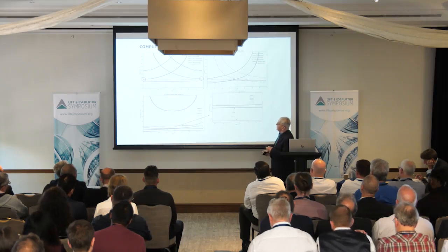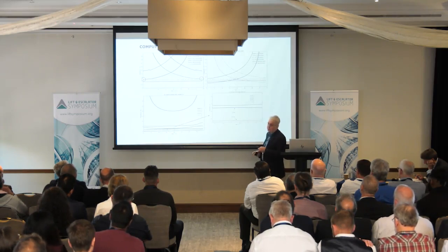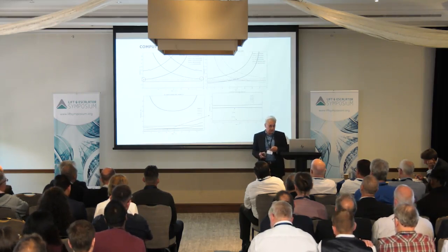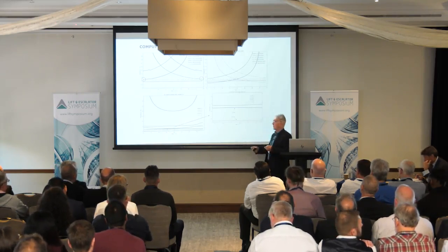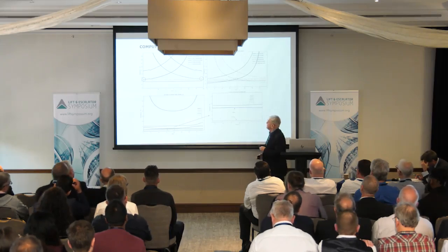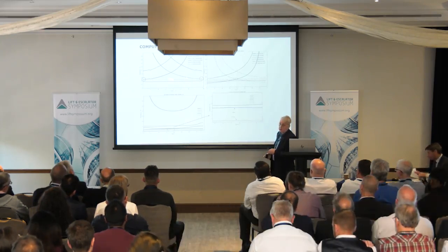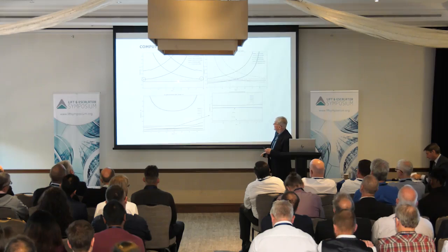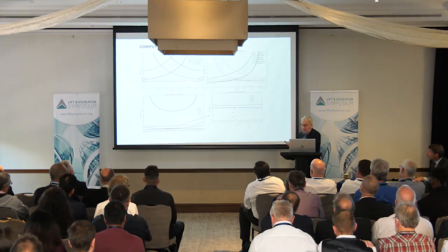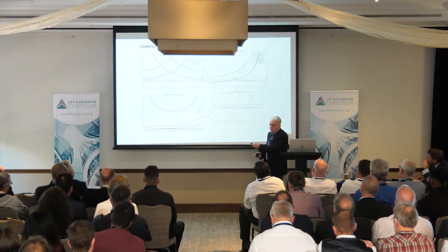If the car is moving down, the frequencies of the hoist ropes on the car side are going down, and the frequencies on the counterweight side are going up. The frequencies of the building here are horizontal lines. That's 0.17, up to about 0.2. That's a very typical situation for the hoist ropes, where at the extreme points of the travel we've got a very close relationship.